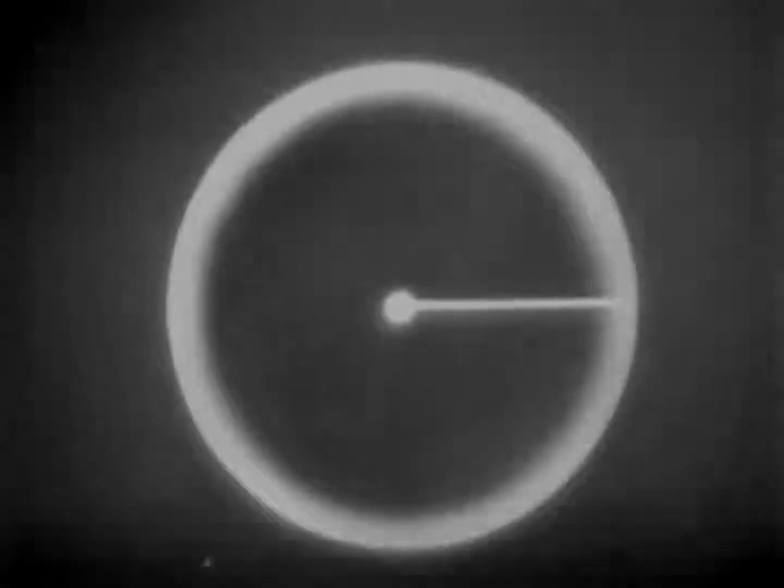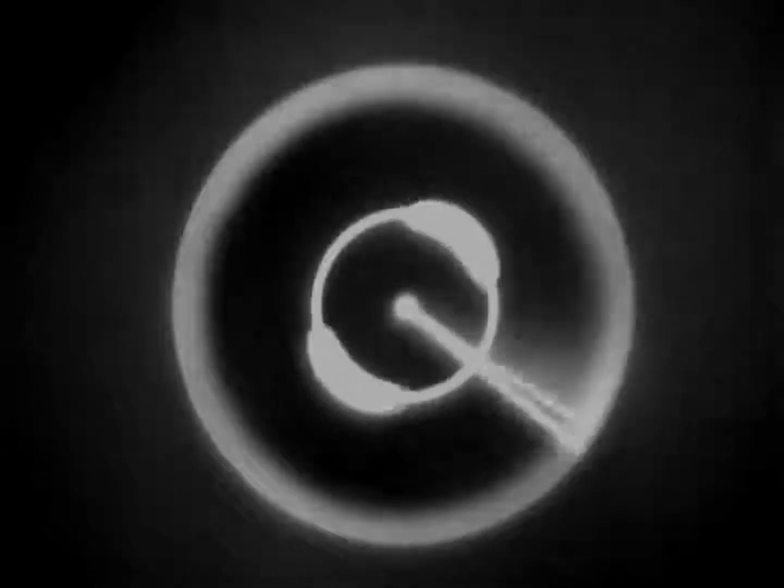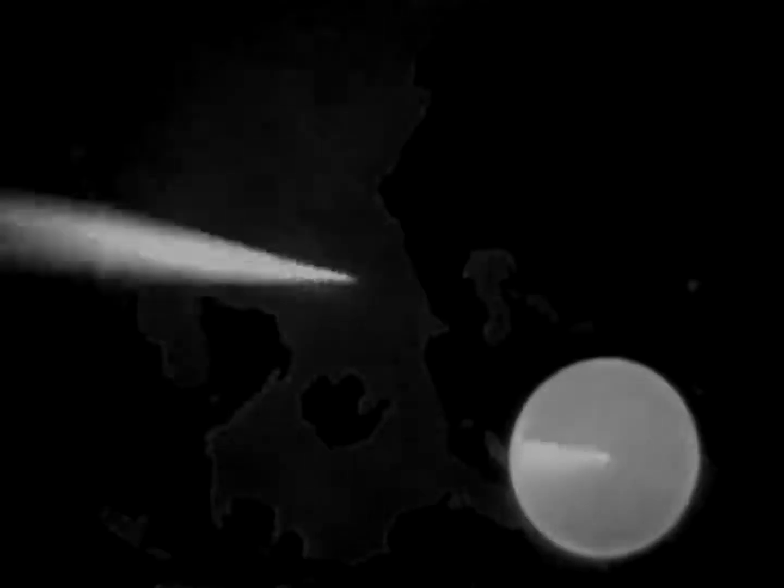But how about azimuth? Well, those coils that cause the electron beam to sweep back and forth to form the baseline are designed to rotate freely around the neck of the tube. Since it was the current flowing through the coils that produced the baseline, when the coils rotate, the baseline sweeps around the scope. The rotation of the coils, and hence the sweep of the baseline, is synchronized with the antenna, so that the baseline is always pointing in the same direction as the antenna.